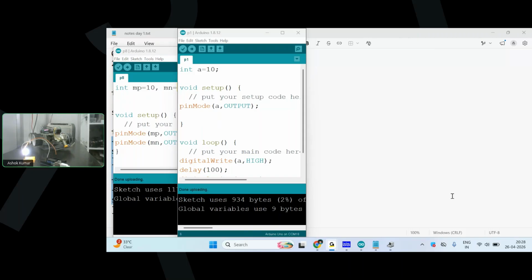Supply is not efficient. Can you please brief, are you talking about voltage or current? See, the voltage is 5 volts and the motor is also looking for 5 volts. So the voltage is equal. What the controller is giving and what the motor is looking for are both 5 volts, which means it is satisfied. So we can connect. But when we talk about the current, that is when we have to think, because when we talk about the IC, this Atmega 328, the current drawn per pin is 10 to 20 milliamperes.